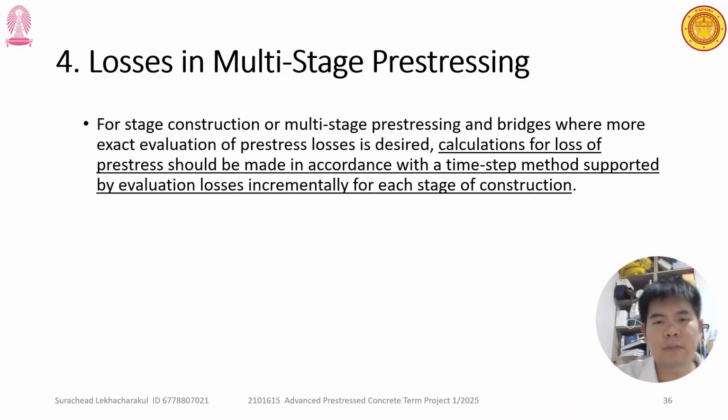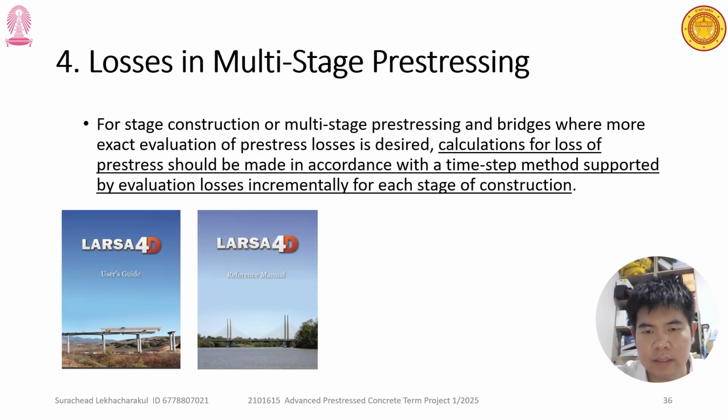Loss in multi-stage prestressing for staged construction of bridges, where more exact evaluation of prestressing loss is desired: the calculation of prestress loss should be made in accordance with the time step method, supported by evaluating loss incrementally at each stage of the construction.